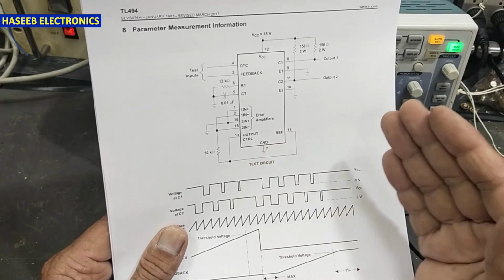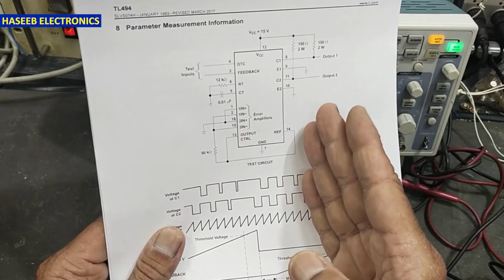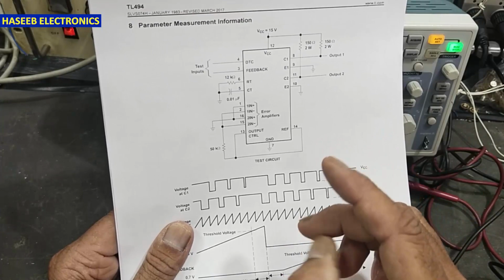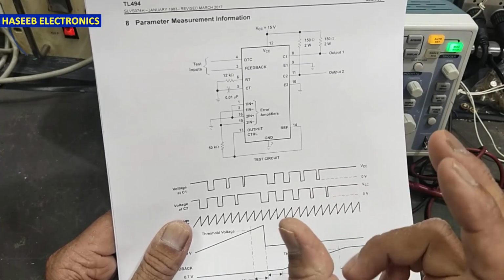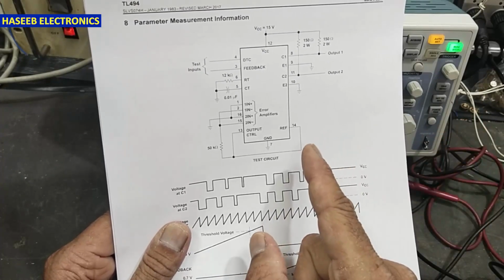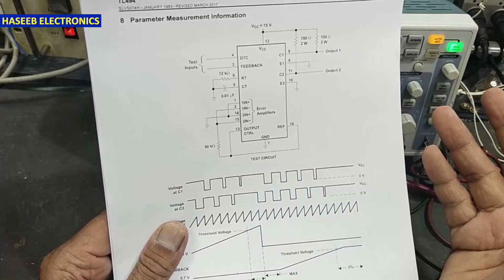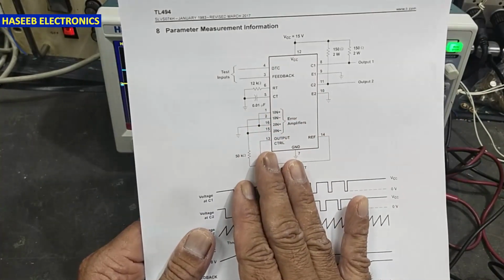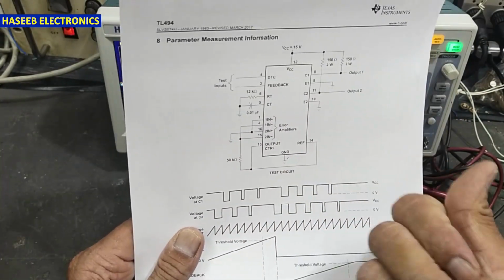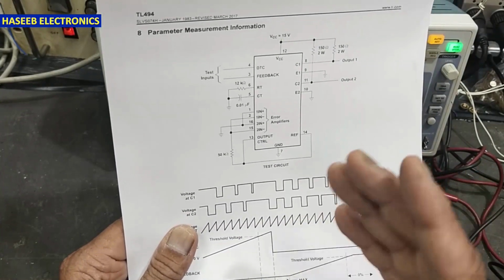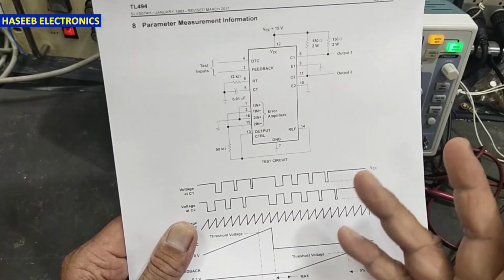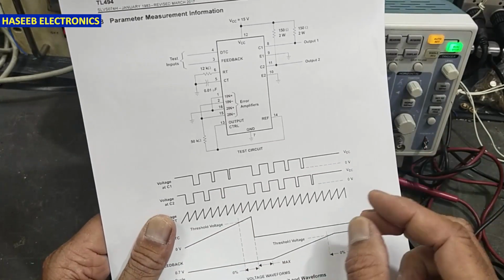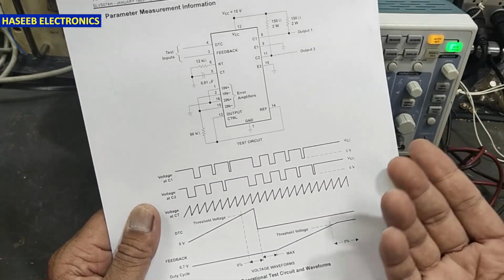If your circuit needs 100 kHz and you are switching at 50 kHz, at that time surely you will damage the MOSFETs. Frequency is directly involved in the switching. If you are not configuring the circuit properly, at that time the MOSFETs will be damaged. Otherwise, if you calculate the circuit properly and inject this signal to the MOSFET properly, then there is no reason that the MOSFET will be damaged. It might be material failure, and it might be a configuration error. If you configured something wrong, it will cause problems.